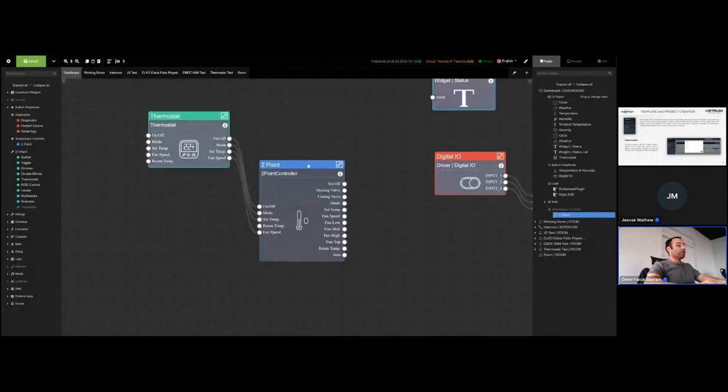If we didn't connect this controller output, controller feedback side to UI input, the end user will not be able to see the status of the control. For example, someone will send on-off, but will not see on-off status because we didn't connect. If we connect this status to UI input, they will be able to see.